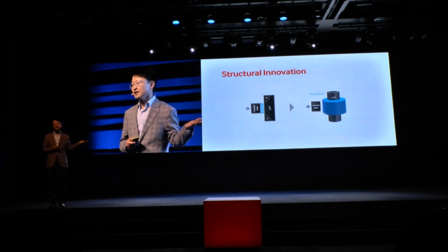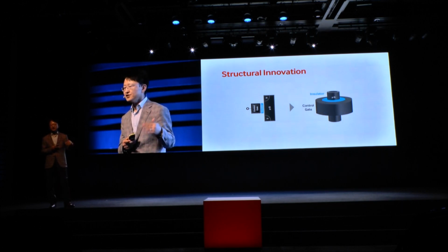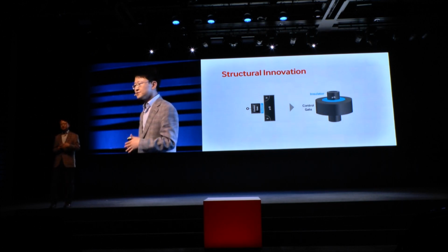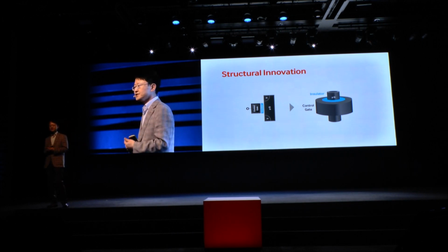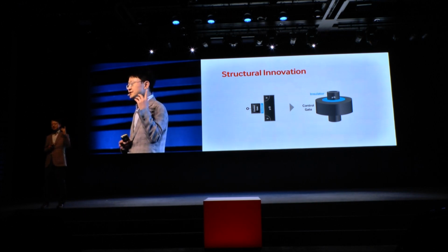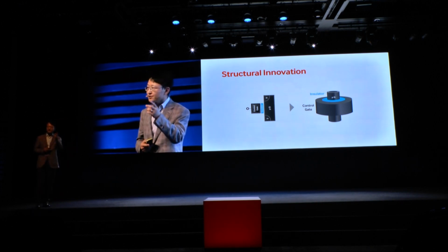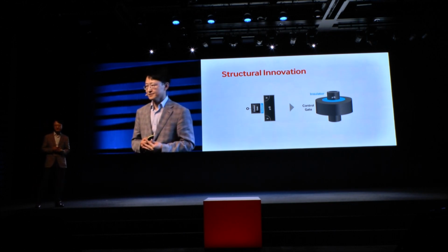The image on the left side of the screen is the structure of a planar CTF NAND. The structure of 3D V-NAND is completely different from 2D NAND, as you can see from the right image on the screen. The structure makes it possible to arrange cells vertically. One thing you should remember is the storage: the storage insulator is covered by a control gate.